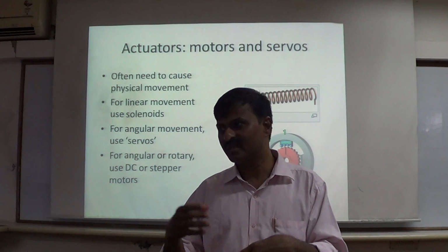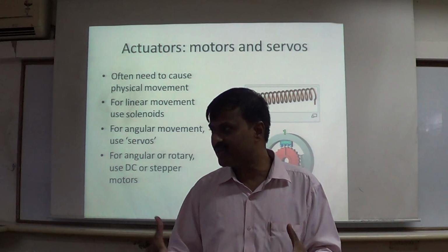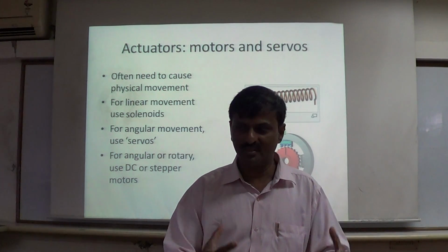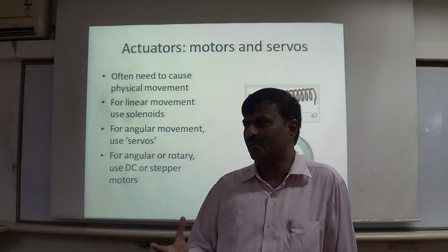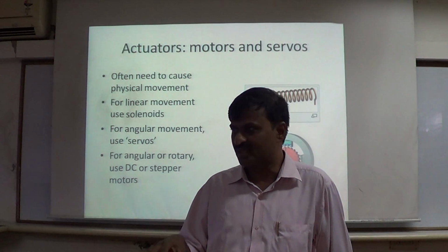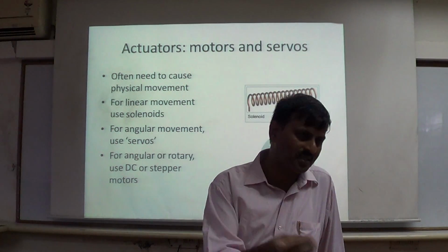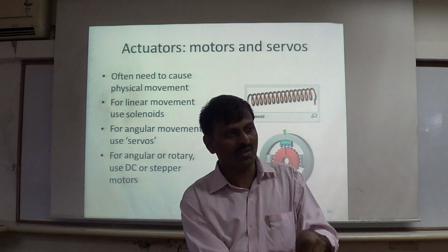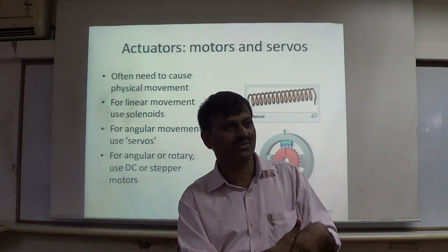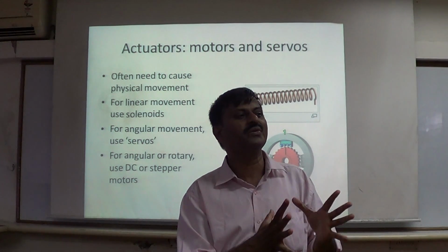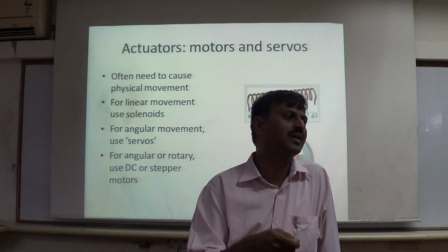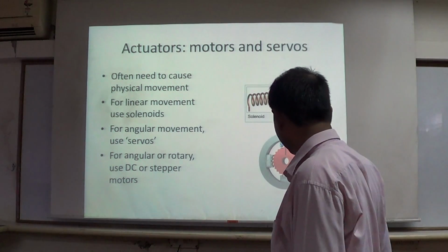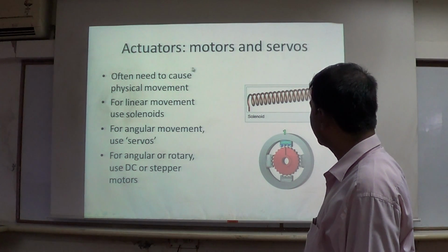So a solenoid valve basically operates on high voltages and high currents, but still due to the magnetic field, that movement is happening, something is getting attracted. It's a valve. The same thing is used in pneumatic and hydraulic control systems. Through those pipes, whenever you want to pass some fluids, there is a solenoid valve, either open or closed. That means the high pressure fluid is passing through that valve. So basically you need to control an inductor. Inductor current you will have to control. Only the shape differs from one application to another. Okay, fine. So it is a coil. All these actuators are nothing but coils.